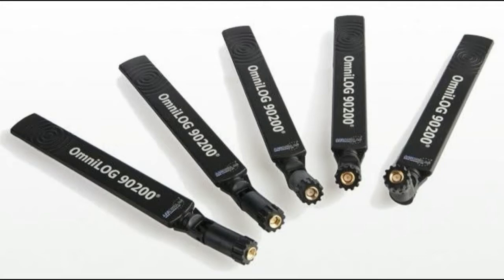To test the reliability of the antenna, we want to see the return loss of the antenna. So first of all, what is return loss? Return loss is the loss of power in the signal returned or reflected by the antenna. The antenna uses a SMA connector, a male type, and the VSWR for the antenna is less than 3:1, the ratio of maximum to minimum voltage of the antenna. And we need to have less than negative 10 dB because less reflected power to the antenna means less interference